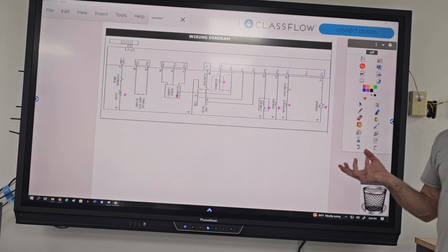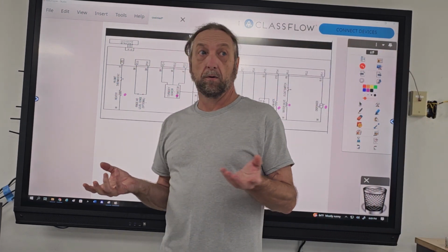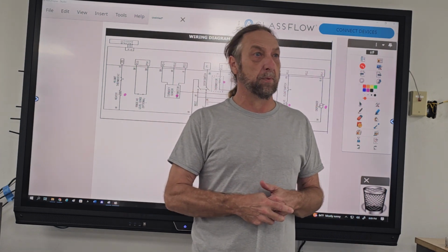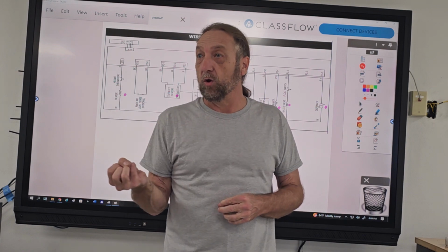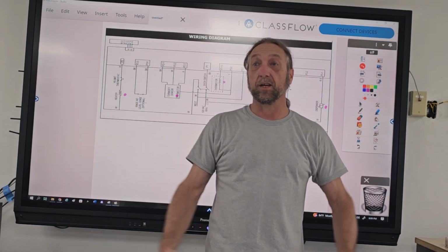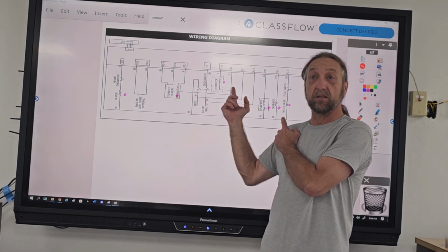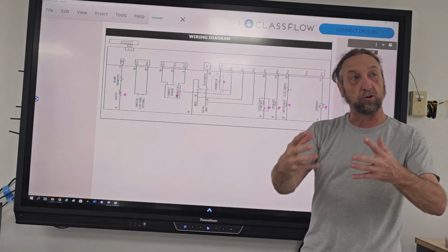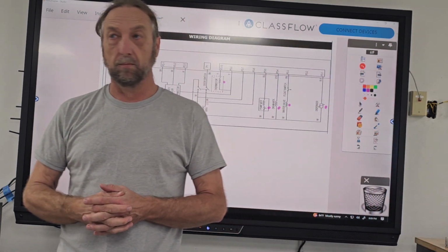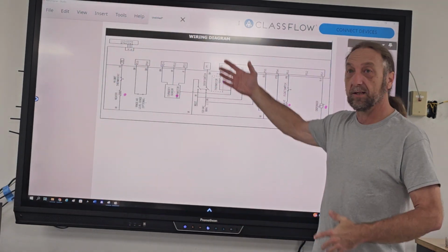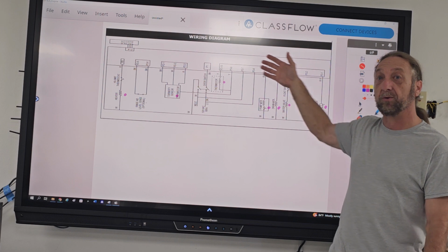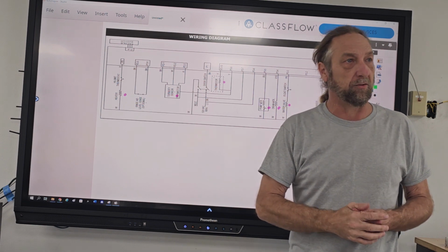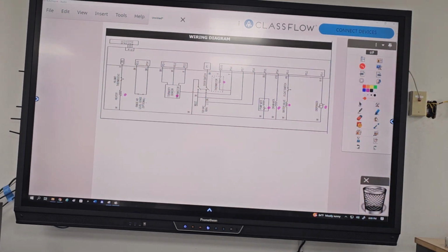There you go. Now, it's both a control and a load. As a load, it lights up, it keeps track of time. If you go to the machine and the machine's dead, one of the things you want to know is, do I have power to my board? It's not lighting up, so my board's bad. That is the load side of it. Somewhere on these boards there's a little transformer that does that. Now, the other thing is, it's a control. It has a bunch of switches mounted on the board that turn on the other loads, which we call relays.